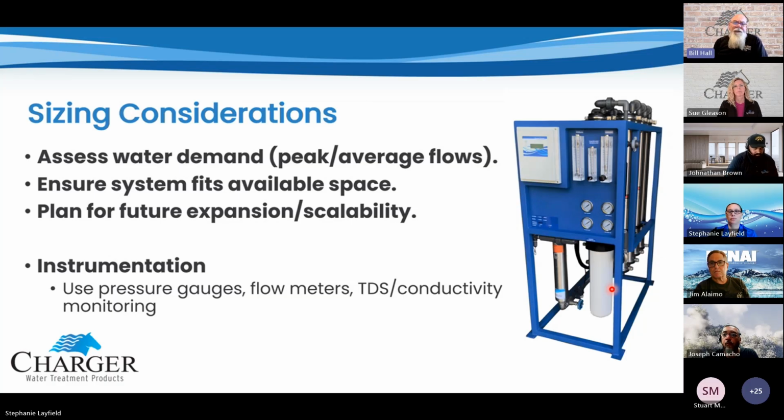One thing that I would keep in mind on a commercial RO would be to have a log. Especially if it's a plant, somebody is going to be walking around checking these things. If you have a log sheet that you fill out every day or every week or whatever the period of time is, you log what's my feed water pressure, what's my pump pressure, what's my permeate, what's my concentrate, what's my TDS.